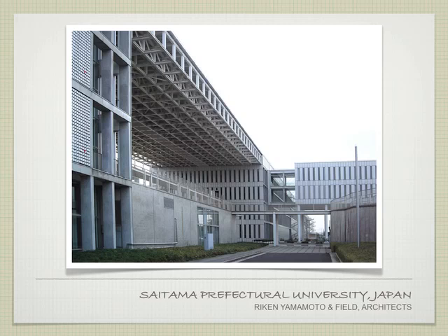That's a steel truss, not concrete, but we'll talk about trusses in a bit, when we get to steel. If we come over to this half of the building, look at the repetition of all these elements. So this whole facade, it's a really long, slender building. We're reusing these elements. They were able to cast all those ahead of time, bring them to the site, and assemble the building very, very quickly.